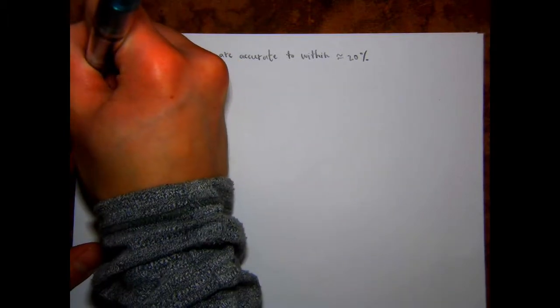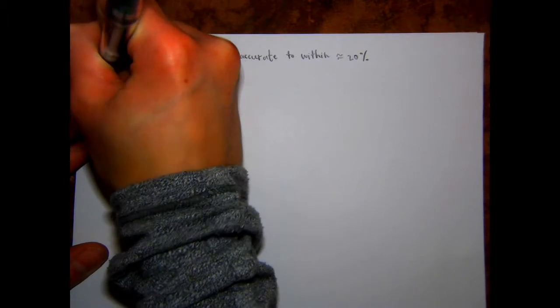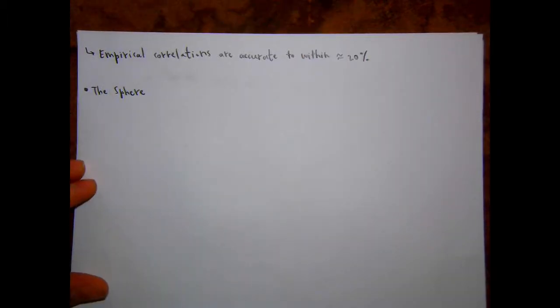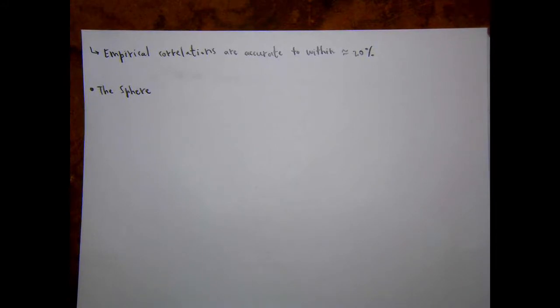Okay, we're going to briefly talk about spheres. So the same kind of boundary layer dynamics that govern the cylinder in crossflow are going to be true for a sphere. You have the same stagnation point upstream, the same boundary layer development under a favorable pressure gradient, then an adverse pressure gradient, boundary layer separation, and a wake forming downstream of the sphere.